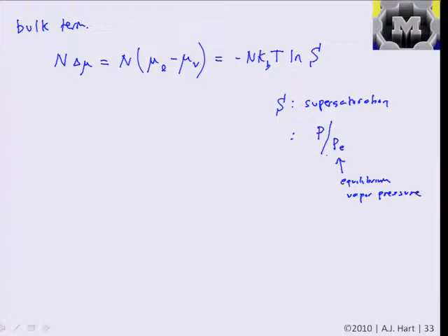Or we are not talking about a bulk surface with a whole bunch of clusters, but we're starting to saturate an individual nanoparticle with precursor that will then start spitting out a nanotube, spitting out that cap or that nucleus or that head of a nanowire when the particle becomes too saturated and has more than the equilibrium state. And this general dynamic of crossing an energy barrier or crossing an energetic threshold is the fundamental event which starts a nanostructure being built from the bottom up.